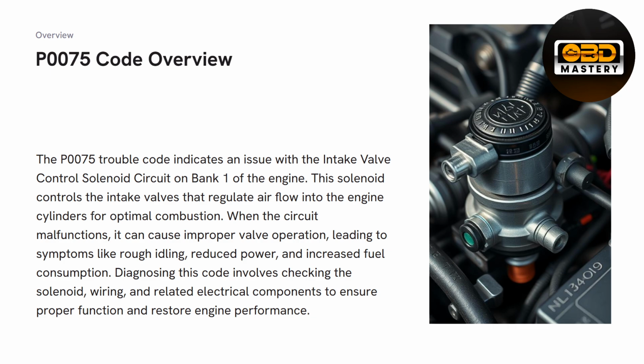P0075 code overview. The P0075 trouble code indicates an issue with the intake valve control solenoid circuit on bank 1 of the engine. This solenoid controls the intake valves that regulate airflow into the engine cylinders for optimal combustion. When the circuit malfunctions, it can cause improper valve operation, leading to symptoms like rough idling, reduced power, and increased fuel consumption. Diagnosing this code involves checking the solenoid, wiring, and related electrical components to ensure proper function and restore